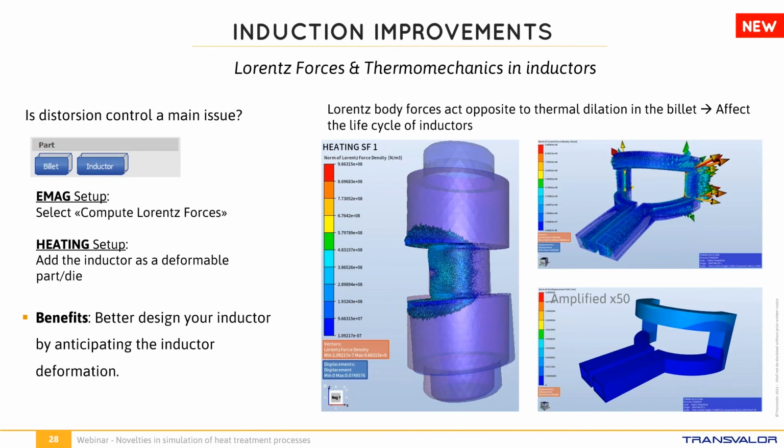From the next release, you will be able to do a fully thermomechanical simulation, taking into account thermal dilatation due to Joule heating, as well as distortion due to the Lorentz forces. Thanks to this development, you will better design your inductor by anticipating its deformation.